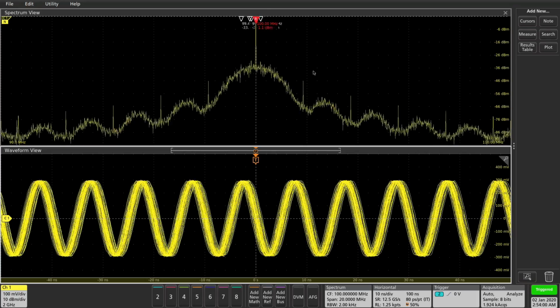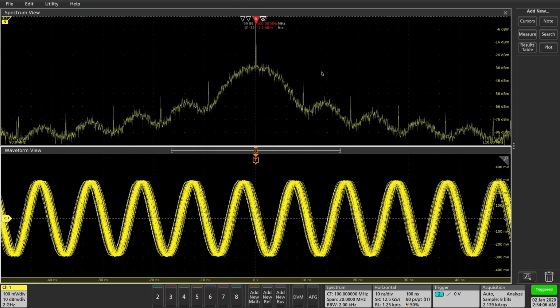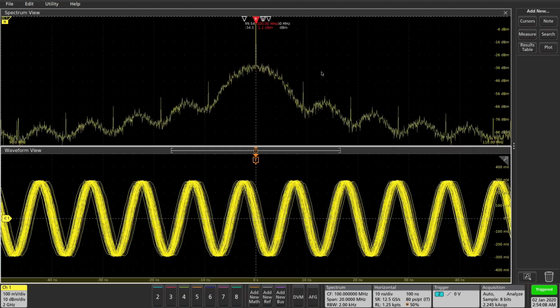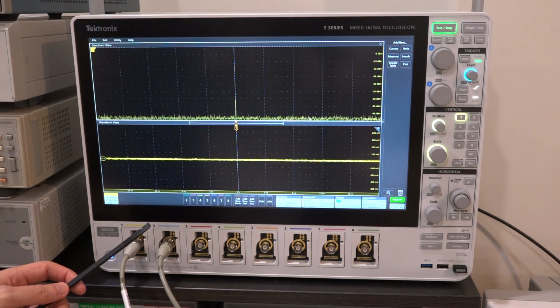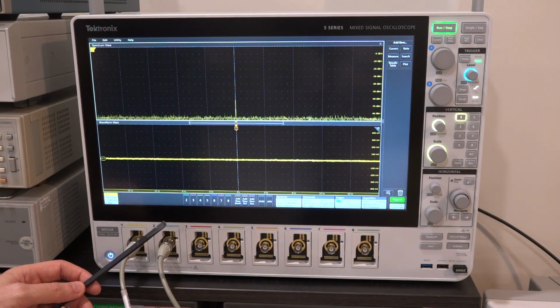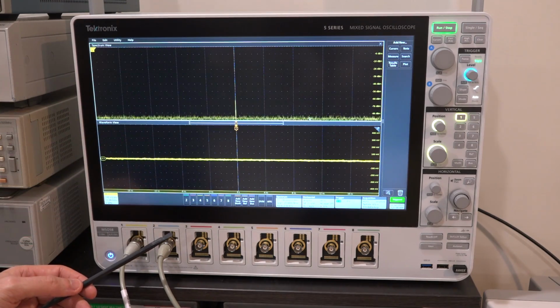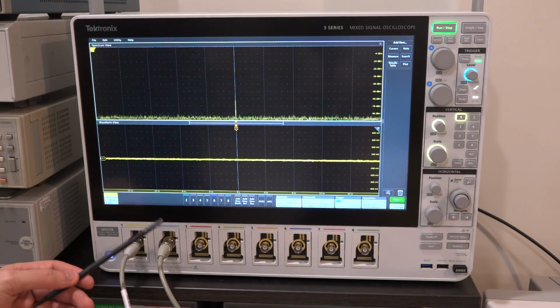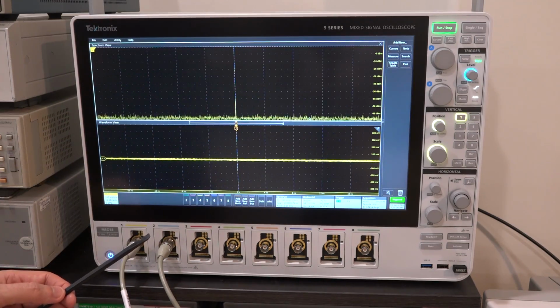So now the question is, well, I'm going to talk about why we don't use oscilloscopes generally to measure phase noise, but then we're going to move on and use a spectrum analyzer. So why is it that people don't use oscilloscopes for measuring phase noise typically? Although people do use oscilloscopes for measuring jitter for data communication purposes, and that's for a whole other video. Well, the main reason is essentially dynamic range, because if you think about it, an oscilloscope is a real-time system. So if you want to find the phase noise, let's say on a 5 gigahertz signal, you'd have to sample that at quite a few times higher than 5 gigahertz and then capture a long stream of data, perform FFT, and then find out how much phase noise you have.